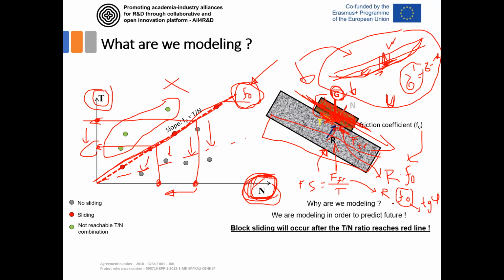Additionally, we can have cohesion in soil. Cohesive soil, like clays and silt, can have a cohesion value. The cohesion value is like when you stick this wood to the concrete. If you use some glue and stick this to this, you will have some resistance even without the self weight of this block. That means you can push it vertically and it will still stand like this if the cohesion is higher than the value of the self weight of this block.